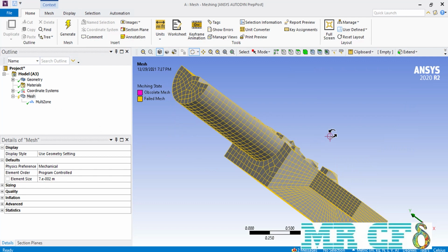Here you can easily see that the software was able to create a structured mesh for the smaller box and the cylinder. It also was able to connect the interior nodes between the bigger box and the smaller box, and between the bigger box and the cylinder. However, the hexahedral mesh cells that are placed inside the bigger box have a very low quality that couldn't pass the quality check test of the software. Therefore, they aren't appropriate for any analysis software to perform simulation on.